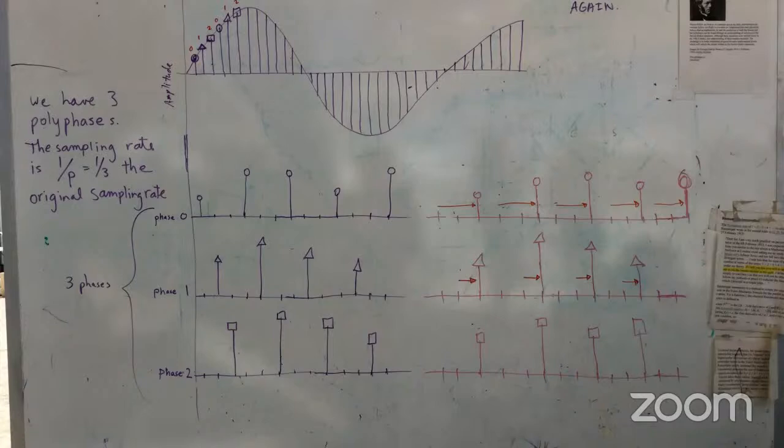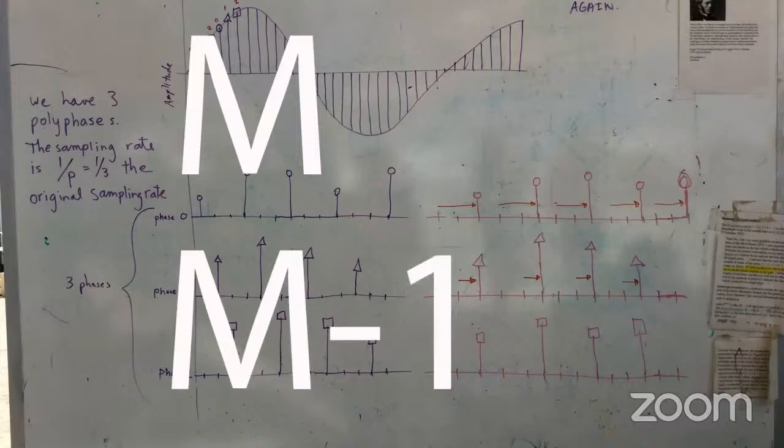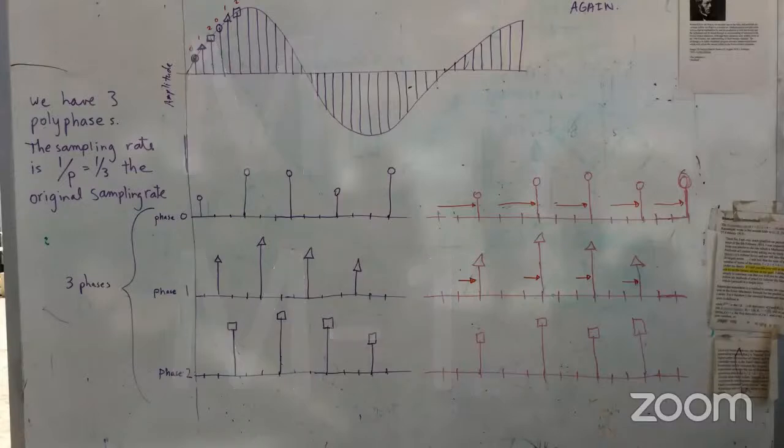Decimation throws away samples. We might get rid of every other sample, every 5th sample, or every 100th sample. It depends on what we're out to do. Decimation reduces the sample rate. Interpolation inserts samples in between existing data. Those inserted samples often have a value of 0. We can upsample a sequence by a factor m by inserting m-1 zeros between each real sample. This increases the sample rate because we have more entries per unit time than we did before. We can also insert samples that are the average of the samples to either side.